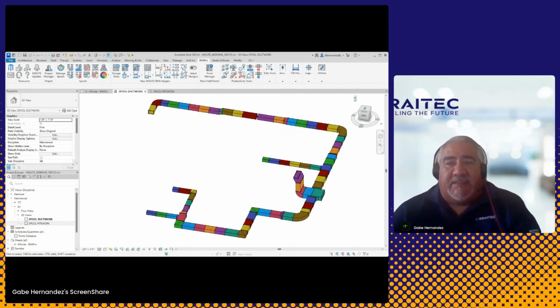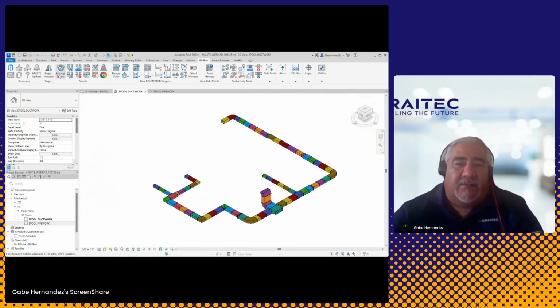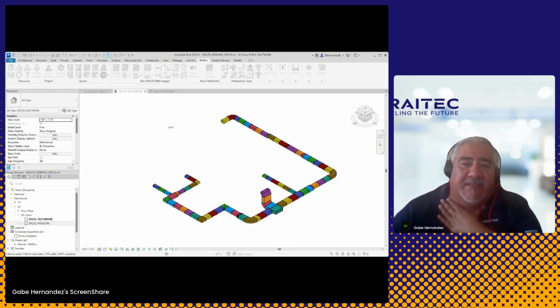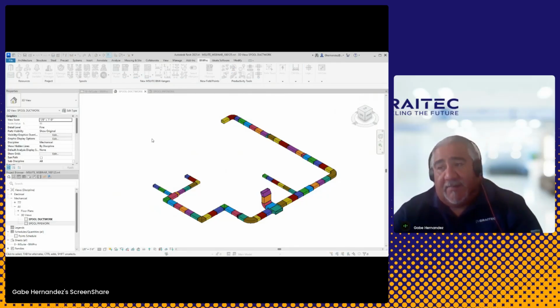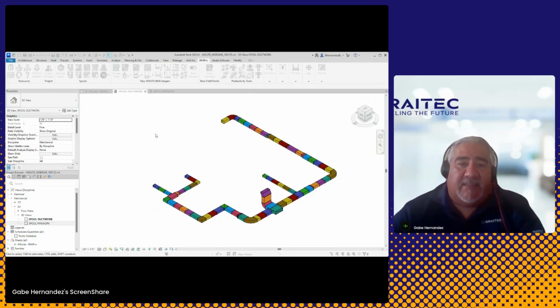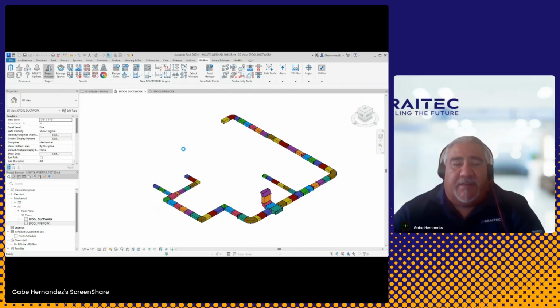And then to produce these spools out, let me go back here. I'll go to the spool manager. So back to the spool manager, and what you're seeing here in this package column is, say, for instance, we call them packages. You may call them prefab packages, but you'll see we can assign these to the actual spools. So real quick, let me get out of this and show you under the properties here. Project Manager, this is where you assign your information or where you set up these packages. So here's my webinar, and then I'll set the package to be like my supply air, level 1 area B supply air package here. And I can say update elements within the package.